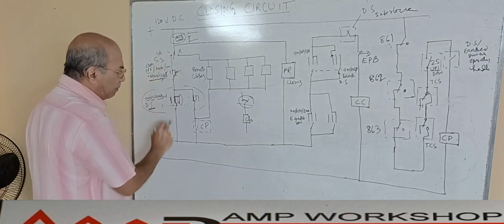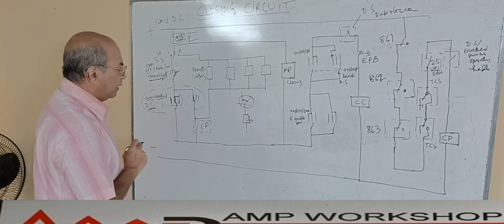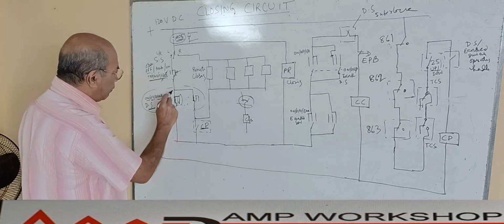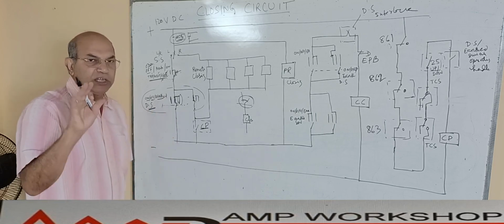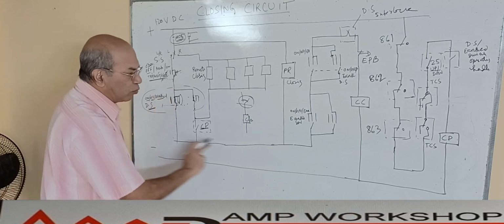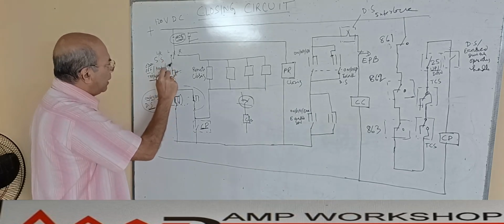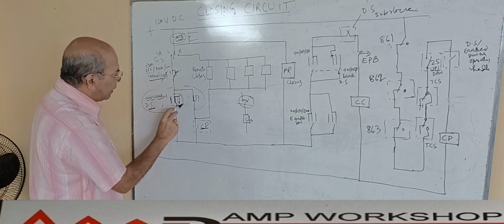So this is the local path, then it is going over here, then after coming over, this is a common path, then there is a permission. When I am testing the breaker, at that time the power circuit is off, so I do not need any other permission, I can go direct to closing. That's why for testing purpose, the path will be this one for the local, then the breaker I am going to close, and this represents the test position.